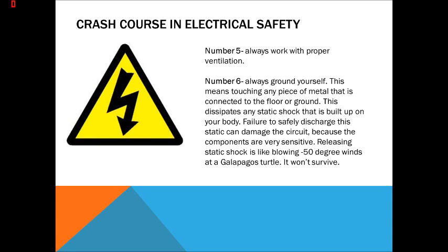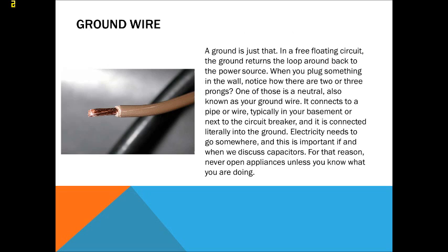This means touching any piece of metal that is connected to the floor or ground. This dissipates any static shock that is built up on your body. Failure to safely discharge this static can damage the circuit, because the components are very sensitive. Releasing static shock is like blowing negative 50-degree winds at a Galapagos turtle. It won't survive.